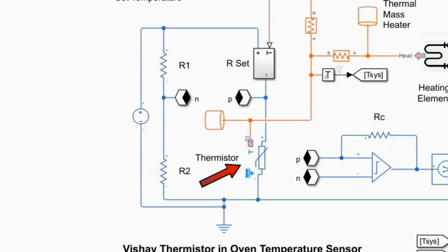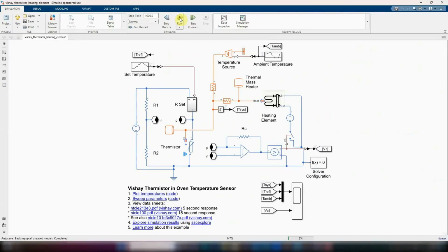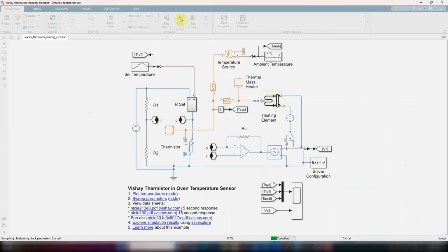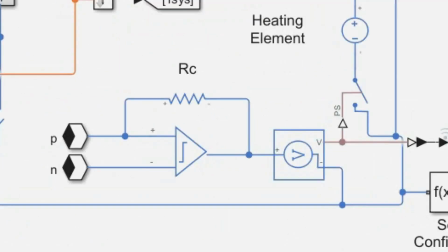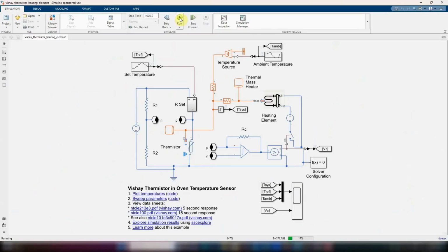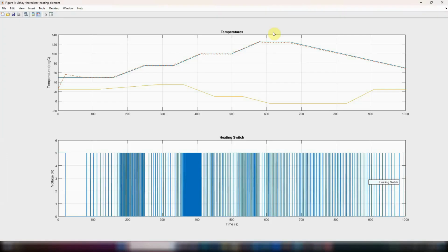The NTC is placed in a Wheatstone bridge and its signal is compared to a given reference signal for a temperature profile reference. The Wheatstone bridge voltage is used by a comparator in order to activate a relay allowing a current to pass through a heating element. This way, the temperature of the heated object will follow the predefined temperature profile with ramps